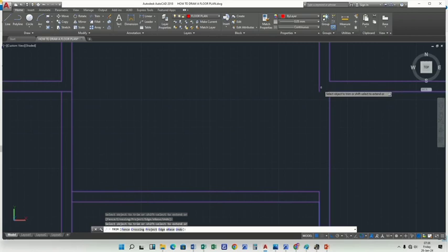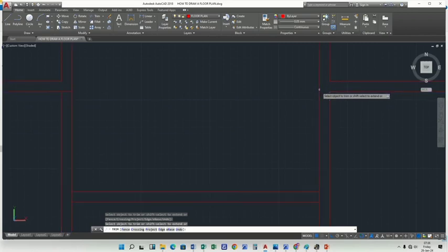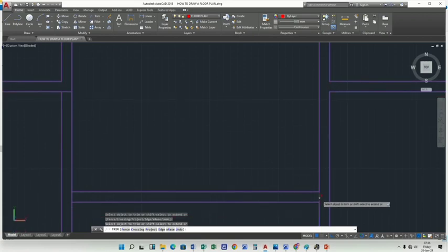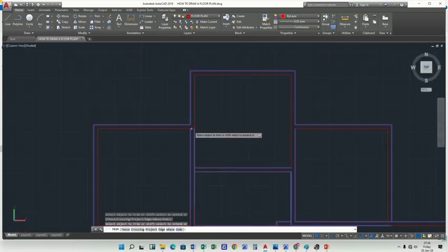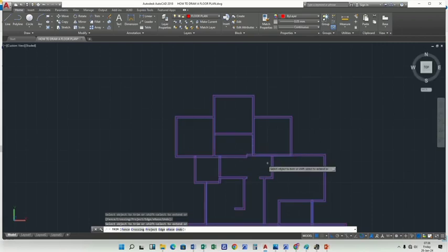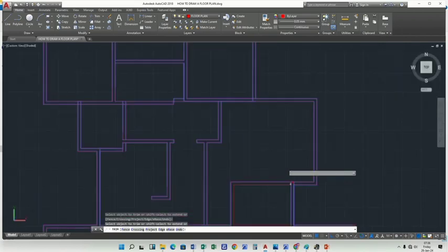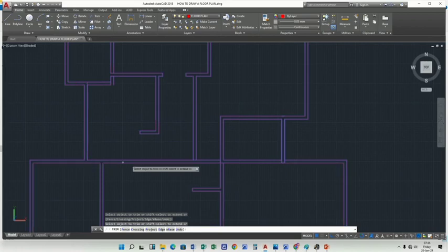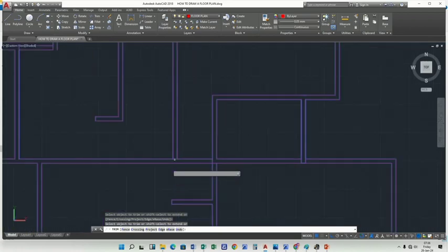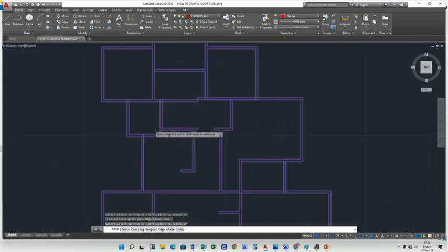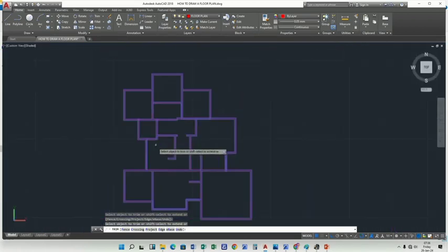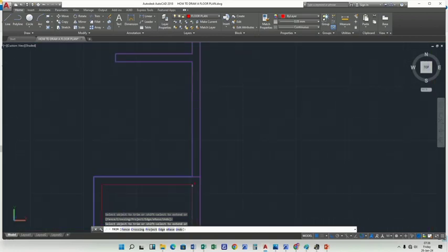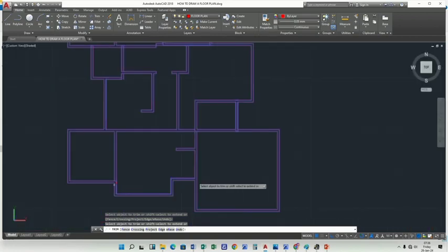Okay, so I've pressed shift to extend this line that I've trimmed accidentally. There is a connection I've trimmed. This side I need to trim also. Trim where you can trim when it's zoomed out; where you cannot see clearly, you zoom in using a mouse wheel by scrolling up and outwards respectively. So there I've trimmed. Where you make a mistake, you type U for undo. Just like that. There it goes.